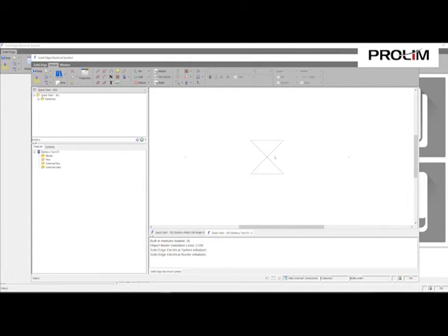And again, here is your origin marker. So this center point right here is going to be the origin point of when you bring this symbol into a diagram. So it's important to keep that point as reference, knowing that that point right there will be the point that you're pulling into the diagram. So again, we can also hit new here to create a new symbol if we wanted to.